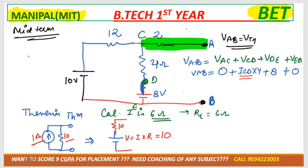Correct? Now see, we need to get the current value ICD. And remember that whenever you need the value for current, always go for mesh analysis. Now if we get the value for ICD, can we get the value for VAB? So how are you going? C to D. Current would also move from C to D. If you are moving opposite, then current will also go opposite. The way you are moving, the current will always go that way. Okay? Now for ICD we can write the mesh analysis equation and solve it.